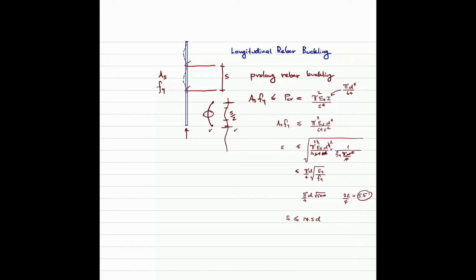The thing is that it is computed by just checking the buckling of the rebar. So to prolong the buckling, we add the hoop. Hoop does serve as the confinement for the concrete core, and at the meantime, hoop also puts the locking and limits the space or the length, effective buckling length of the rebar, such that the longitudinal bar will not buckle at very low stress.